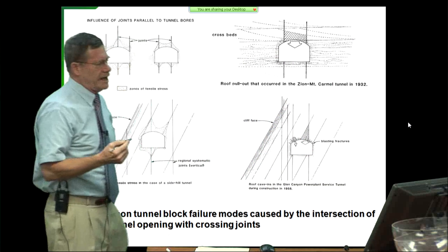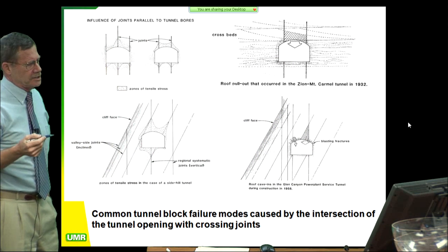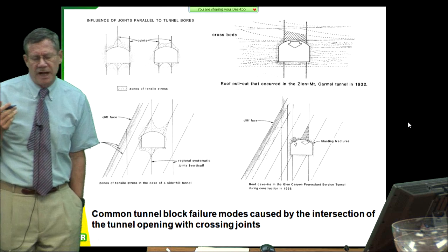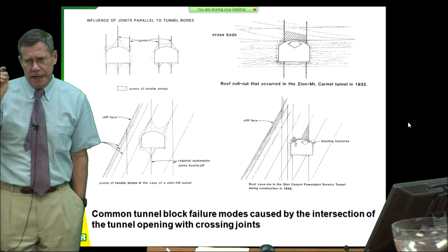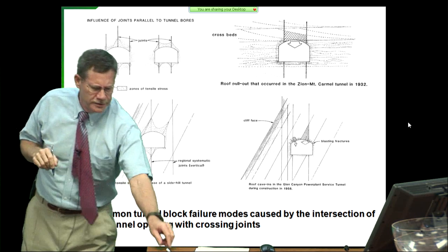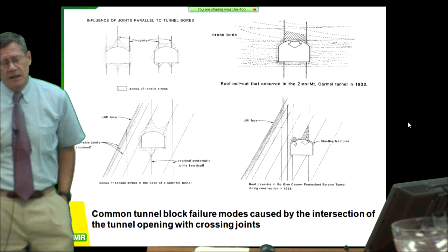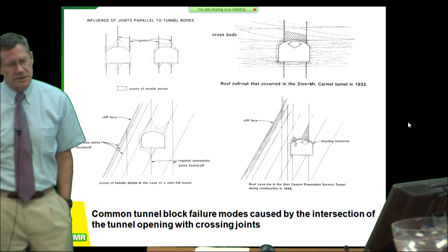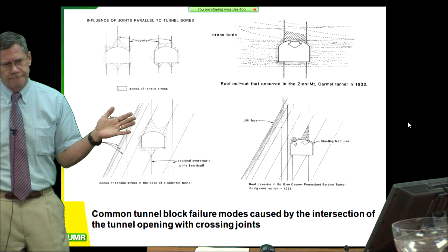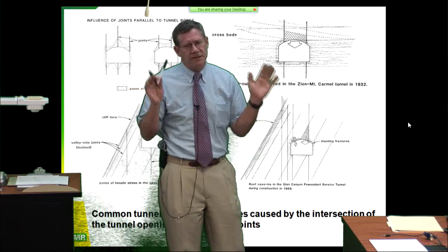What we want to do is constantly draw the situations, sketch them. What we do today, I always have my geologists take pictures and then draw with waterproof pens on the pictures. So you draw right on the pictures, and you do that the same day. Don't let your pictures accumulate for a week. You will forget 70% of the stuff you want to take note of. You have to do it the same day.